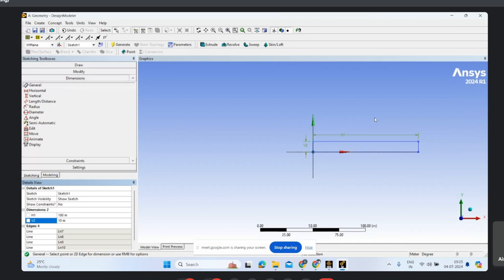So it knows certain things. It will select accordingly to its preferences, according to its programming, which is the inlet, which is the outlet, what type of analysis we are doing. So now we should specify whether it is an external flow or an internal flow. We need to specify that first. I want to see how either water or air is flowing inside a channel or a pipe.